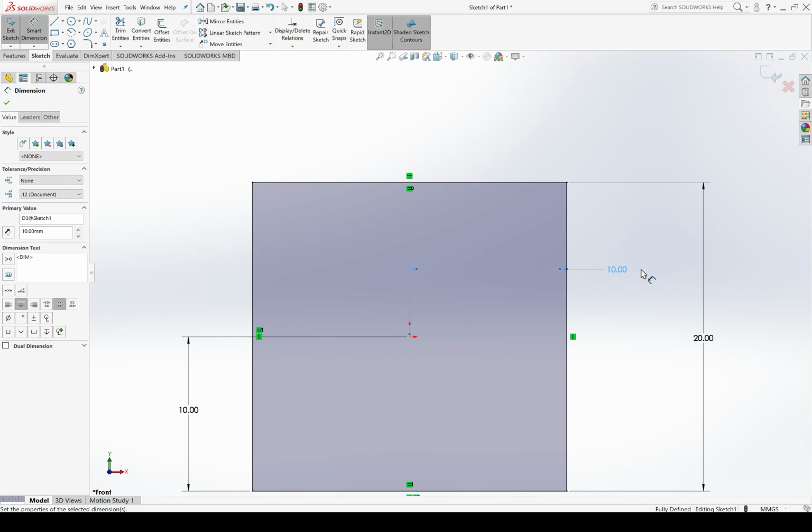For example, if this cube being 20 millimeters on each side wasn't actually what I needed to accomplish whatever purpose I'm creating the square for, if I needed to resize it down the road, maybe to 25 millimeters or 30 millimeters or what have you, all of a sudden the origin is no longer centered. So if I were to define the origin as the actual center instead of a distance and offload the math onto SolidWorks, then it could accommodate those changes down the road.